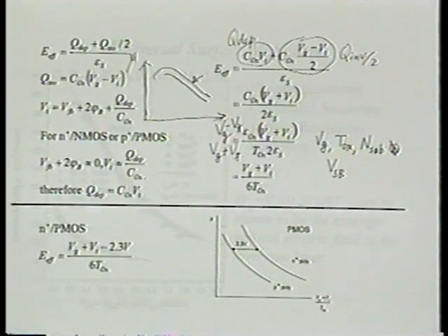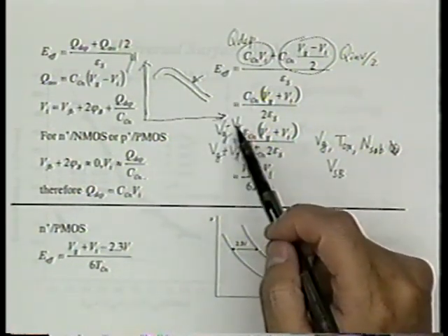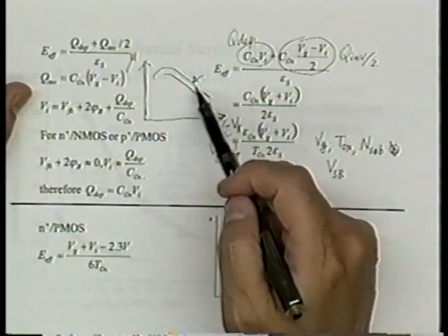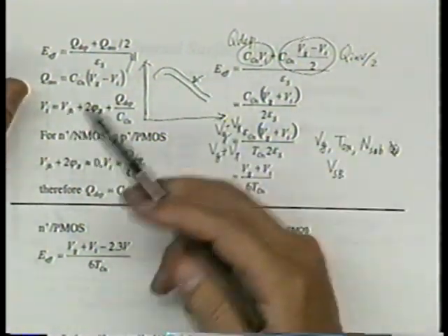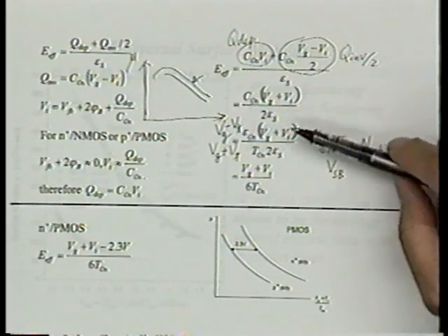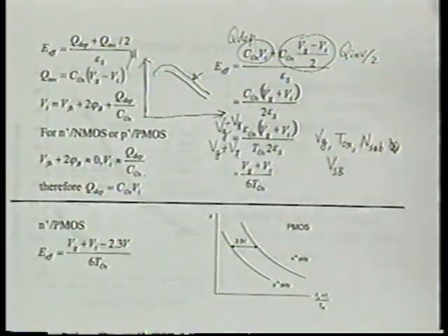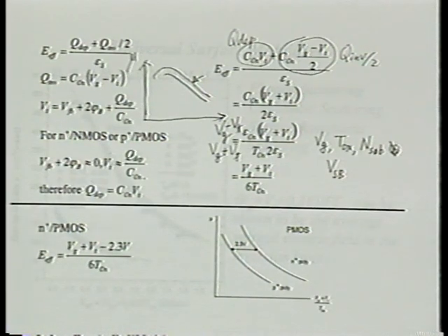Okay. If the VT has differed by 0.2 volt, whether you use plus or minus VT, you will shift one of the curves by 0.4 volt. You can easily reverse the conclusion. That's, again, the reason why we want to know the theory behind certain things before you plot it, right? It's not just to say, because we see VG minus VT a lot, therefore, in mobility comparison, also plot VG minus VT. It should be VG plus VT.